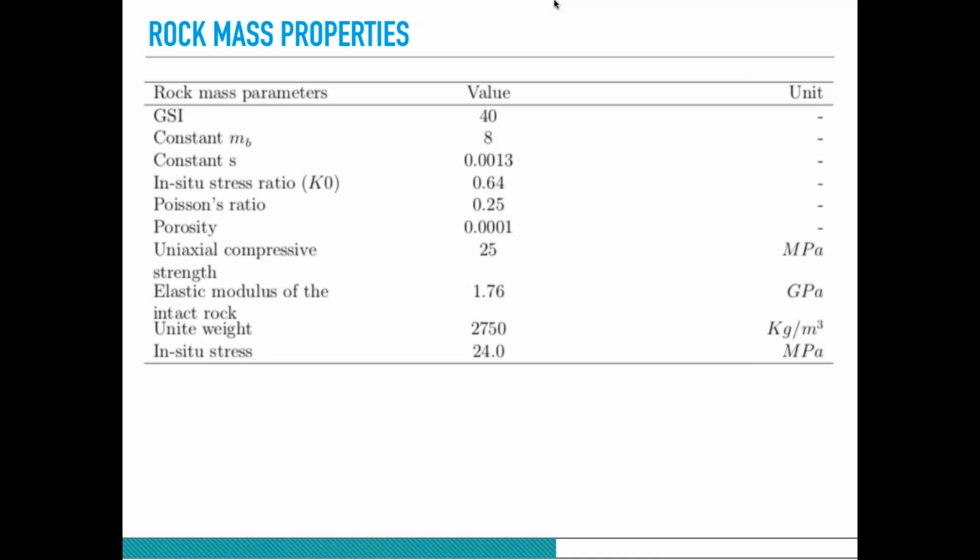These are the parameters for the rock mass. The way I have decided to model the rock mass is Hoek-Brown, since I had the parameters for the tunnel for Hoek-Brown. You can also use Mohr-Coulomb, but you have to consider the creep behavior of the load.